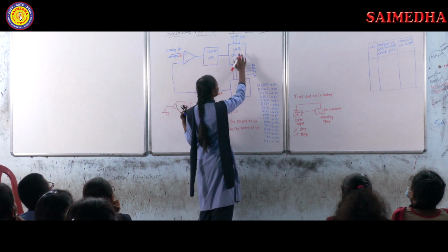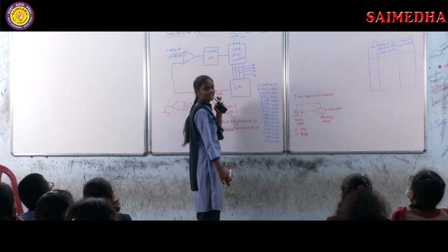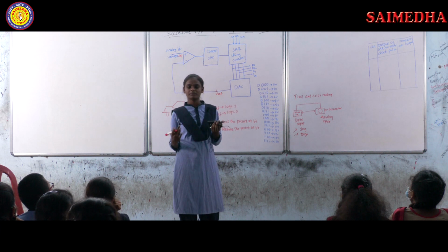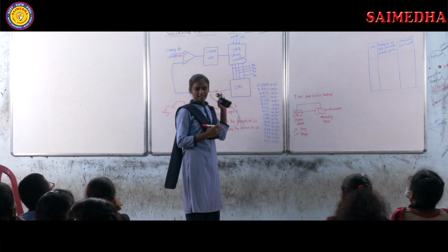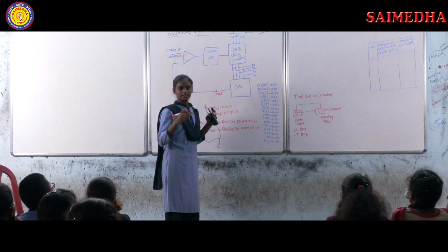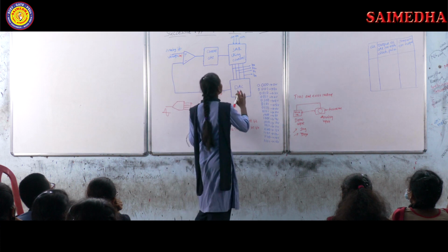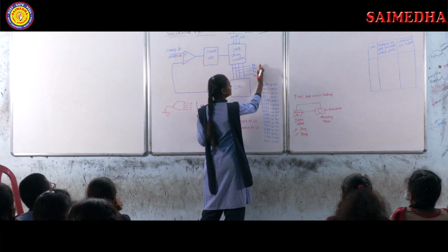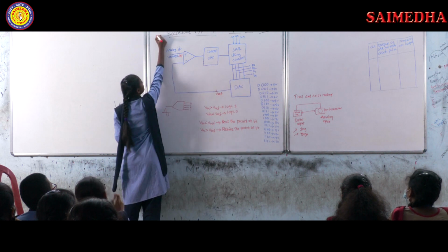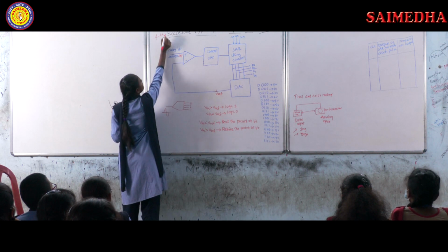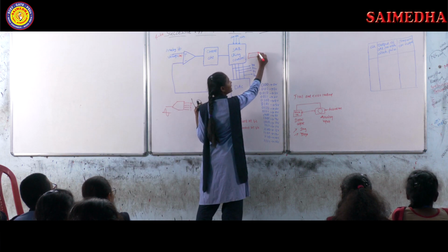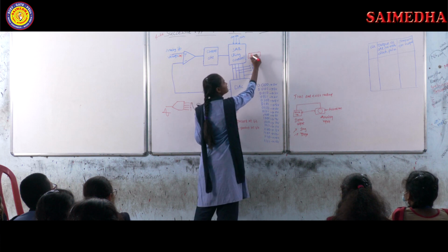A successive approximation register contains a ring counter, which is successively set one bit at a time from MSB to LSB. Basically, it starts from the MSB and next transfers to the LSB. And here we are taking 4 bits, so this is also called a 4-bit successive approximation register ADC method. The ring counter contains 4 bits, that's why it is called 4-bit.